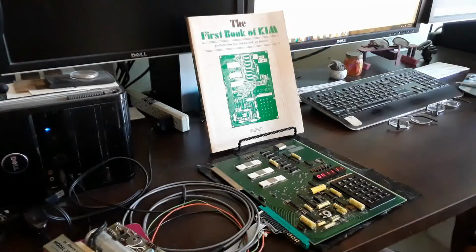We also learned how to view the internal registers of the 6502 processor by accessing memory address 00F3 to 00F5. Then we learned how to simply go back into our program by pressing PC or program counter key so that we can continue executing our program where we left off. So you see, this first mini program really taught us a lot.